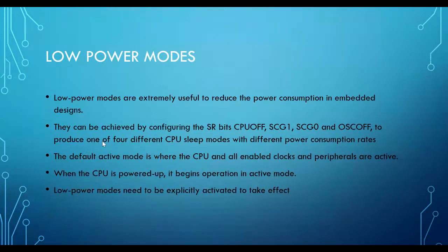Now, apart from this, we finished discussing relocatable codes and these functions, macros. We want to look at another issue, which is the low power mode. Low power mode is extremely useful to reduce power consumption. Now, when you're designing embedded systems, power is everything. You have an Arduino or whatsoever, and if you just use a meter to measure it, you find that the ampere draw is very high. So your battery will dry off in a very short time.